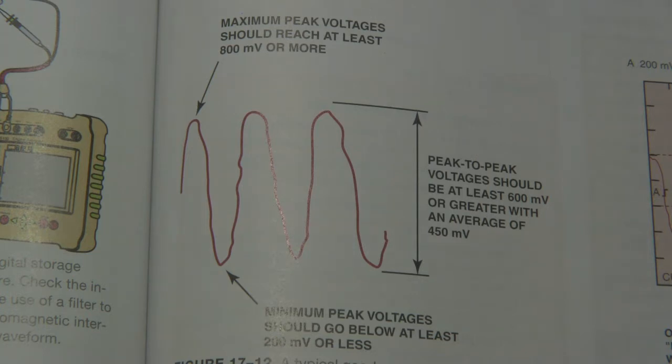You're going to have carbon deposits. You're going to have maybe a little bit of junk in the fuel and it doesn't burn quite right. And so there's going to be a little bit of fluctuation in there that the computer's allowing for. Once you get past a certain threshold in the code enabling criteria, that's where you're going to get a check engine light that comes on. So if you have a vehicle that is marginal, meaning that it's just right there on the edge, it might turn on a check engine light and then the problem can kind of go away.